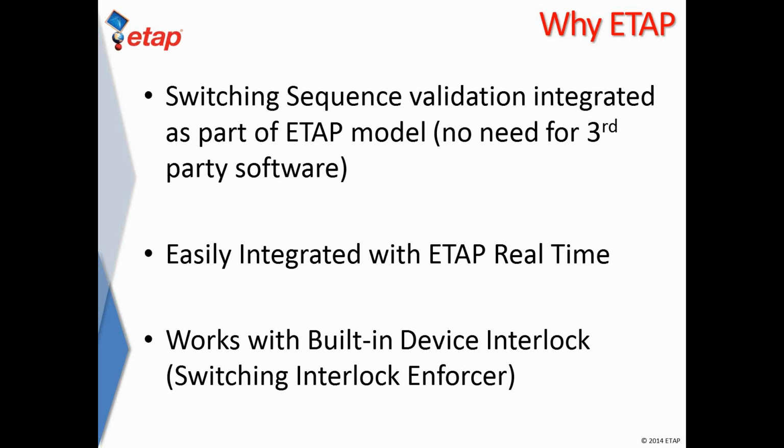The same one-line diagram, the same ETAP project that you've been using for arc flash, perhaps that is being used for short circuit and load flow, to do the planning and the design, can also be used to perform the switching sequence validation, right?